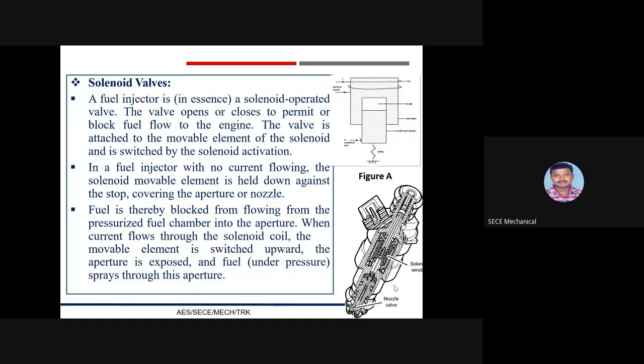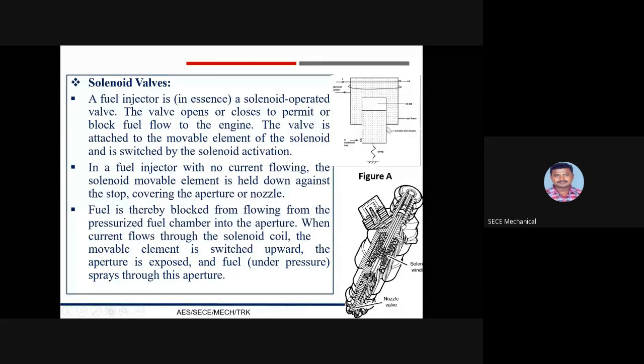Here, we are also going to control the fluid flow or fuel injection with the help of this solenoid valve. In the fuel injector, you can see the nozzle, and the solenoid windings are around that nozzle. The plunger is also there. Here you can see this is a coil, and electrical current is going to pass through here, and then this is the air gap, and this is a movable steel element. You can also call it a plunger, and here we will have some mechanical load, and this is a spring actuator solenoid valve, and this is the air gap.